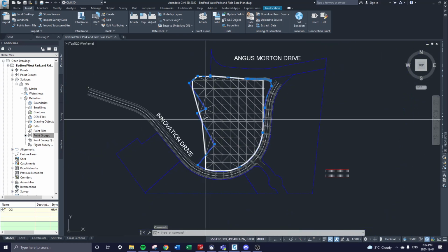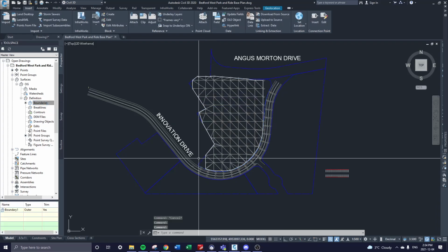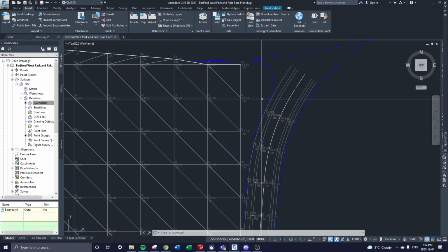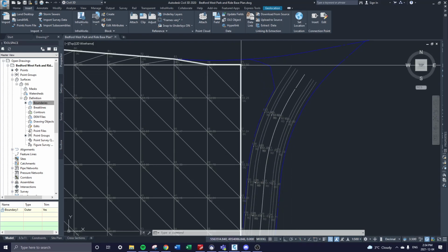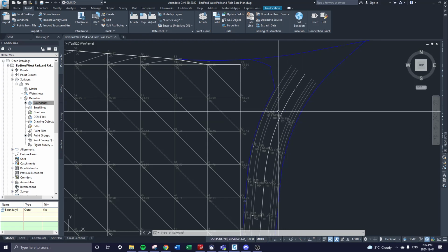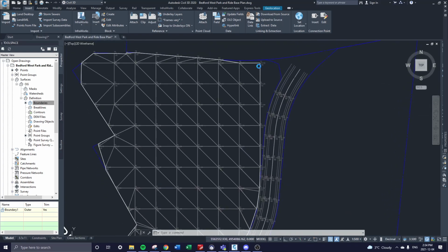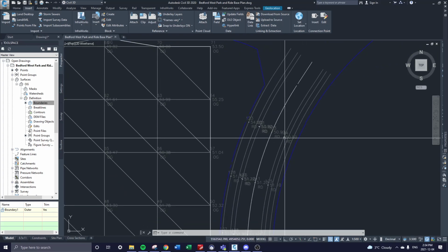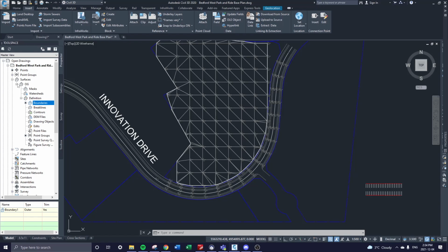So we're going to click this property boundary that we have, and over in the surfaces, we're going to add that. What that will do is trim just the exterior where it's not relevant. And you see there's no information here. If you included the road, then it would triangulate a little bit, but the existing grade point here and the road point there, that's not a very accurate contour line, you know what I mean? Because you're going from 53.5 up in the lot, and then you're going down to 50.8, which looks like the asphalt curb. So that's why I like doing two different surfaces.